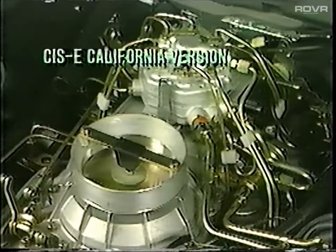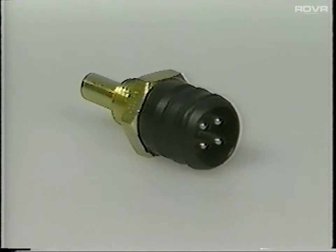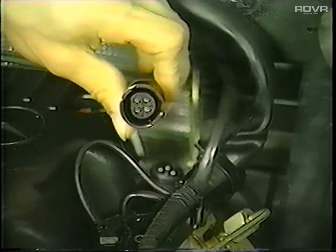There are 3 changes that relate to California version engines, and it must be emphasized that the following information is only applicable to California version vehicles. The first change applies only to the V8 engine and is the addition of a temperature sensor in the EGR pipe. The sensor measures the temperature of the recirculated exhaust gas and sends the appropriate signal to the CIS-E control unit. A 4-pole temperature sensor is a new development and is installed on all California version engines. The plug can be inserted in any orientation.